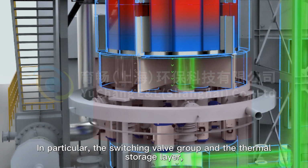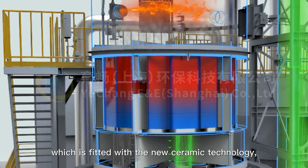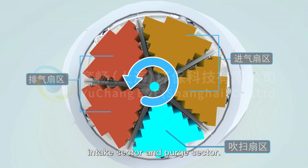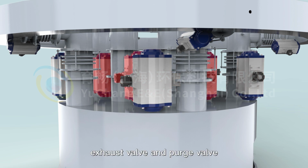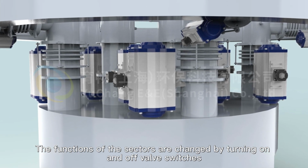In particular, the switching valve group and the thermal storage layer, which is fitted with the new ceramic technology, can be divided into multiple sectors, which alternately and cyclically serve as the exhaust sector, intake sector, and purge sector. Each sector is separately equipped with 3 valves: intake valve, exhaust valve, and purge valve. The functions of the sectors are changed by turning on and off valve switches.